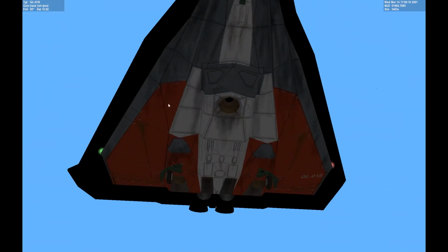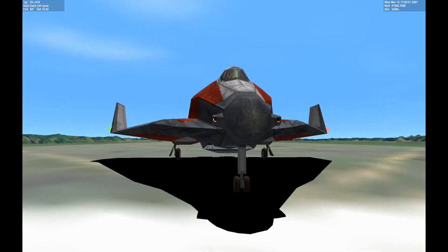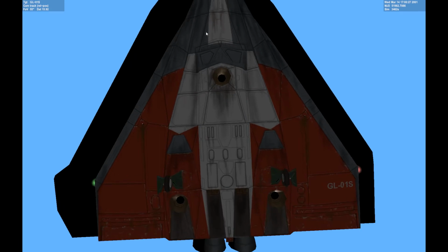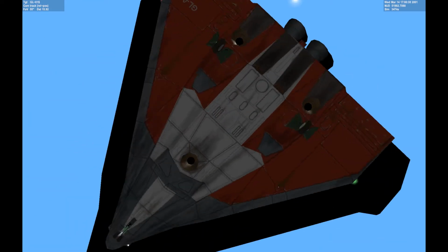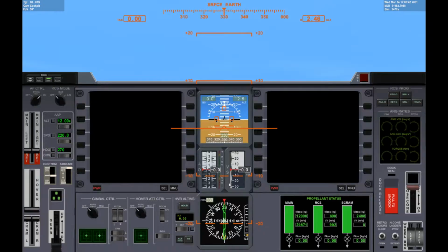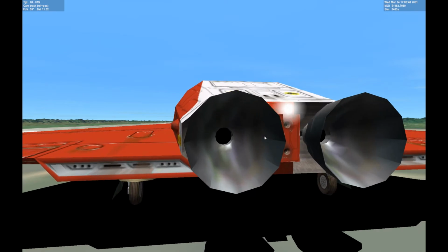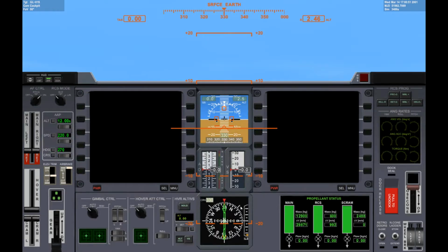So what is a scramjet? Basically, you have some fuel on board, and you scramble some oxygen into this chamber. Because of how fast you're going, the air compresses itself down here. You throw the mixture of gas in, and it automatically ignites because it's already compressed, and it just comes right out the back. And you get thrust. Our main fuel is somewhere up in this chamber here, and it comes out here. It's got oxidizer as well. So scramjets only work in an atmosphere, only in a thin atmosphere. Rockets can work anywhere where the atmospheric pressure is lower than the chamber pressure.